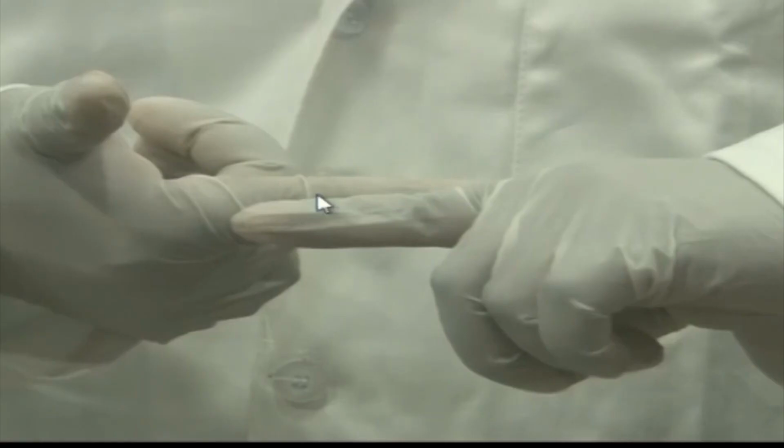So this is kind of an overlap. The second layer wouldn't be exactly on top of the first layer, it will be a little overlap. In this case, you can just see like the fingers, we are just trying to demonstrate that 50% overlap can be seen here, but 15% of exact overlap would be there if we put this input in the machine. So this bead is deposited in this way. Sticking the layer would not be proper if this overlap is not there, and the proper overlap is 15%. Then there is an overhang angle as well here.